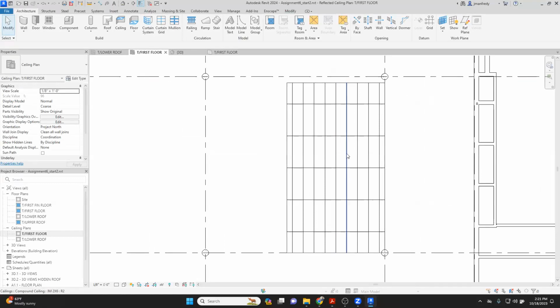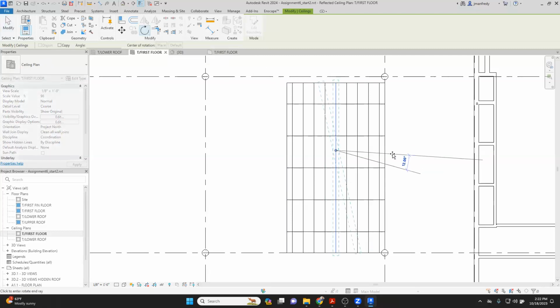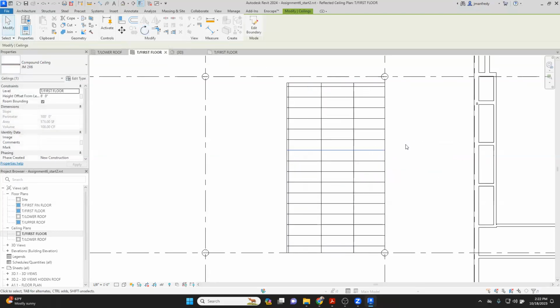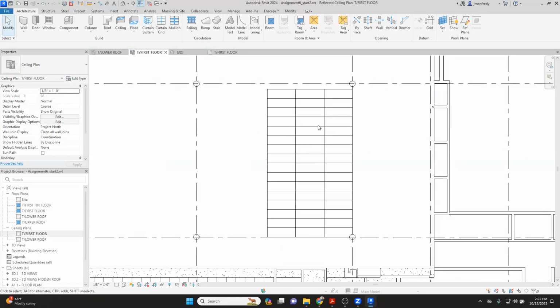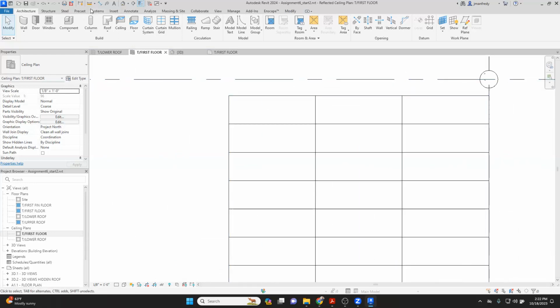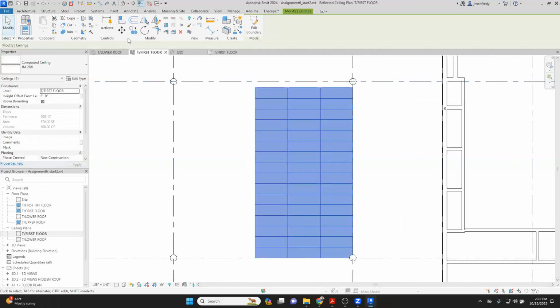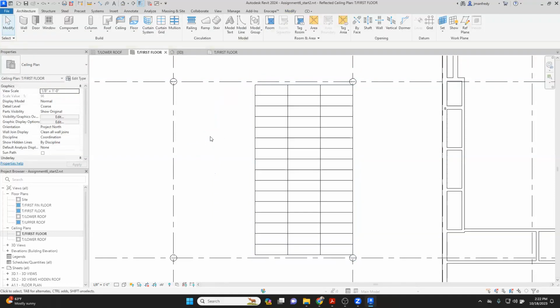So you can quickly change that by grabbing one of these grid lines and rotating them. Just start anywhere on the screen, and type 90 degrees. And then make sure it aligns, line it up to the edges just so it's nice. So there's the ceiling so far. And then here, I want it to be centered between these grid lines. So what is this number here? Just do a little tape measure. What is this? 14 inches. So half of that, I need to move this up half of 14 inches, which is 7 inches. Okay, so there, now it's centered.